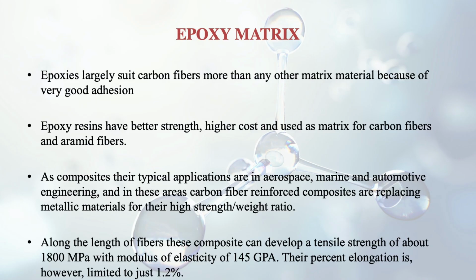Along the length of the fibers, these composites can develop a tensile strength of about 1800 megapascal with a modulus of elasticity of around 150 gigapascal, and their percentage elongation is limited to just 1.2%.